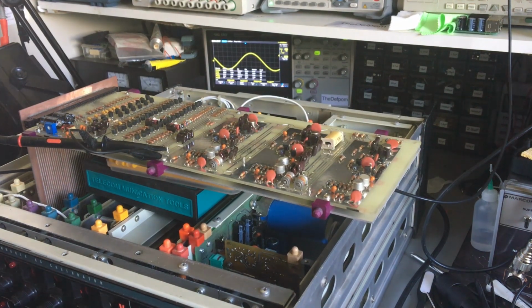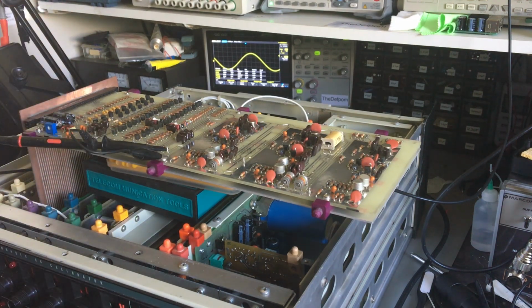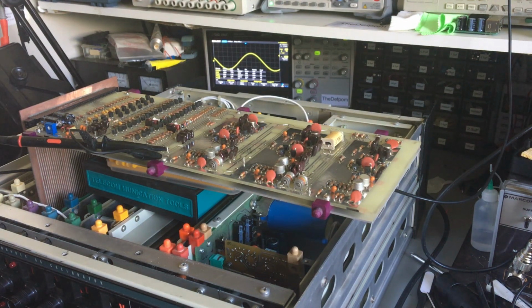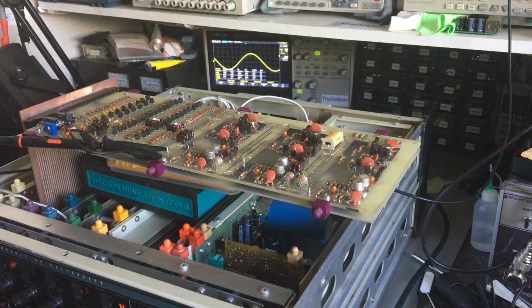Okay, so the previous test was on 100 kilohertz. Now I've changed to 10 kilohertz, because this goes to some slightly different frequency control, and it's got some relays which click in on the oscillator control board. And as you can see here, I've got 6 volts at 10 kilohertz coming out. I've got 10 kilohertz going in on the 10 kilohertz range. Right, we change ranges, it disappears.